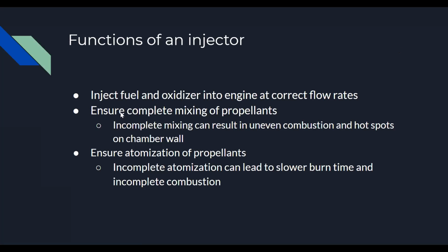Another important thing is that it needs to make sure the propellants are mixed completely, as incomplete mixing will result in uneven combustion. Parts of it will be fuel rich, parts will be fuel lean. You'll get hot spots on the chamber walls that will lead to uneven heating there. You won't get the exact combustion reactants that CEA is giving you, and that's no good. So the injector really needs to make sure that the mixing of the propellants is complete.